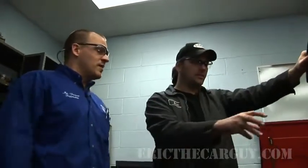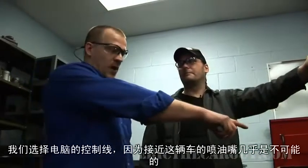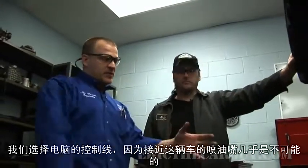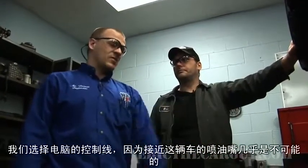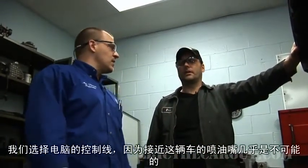We still might be able to zoom in on just the injector. Why would that be difficult? It's not difficult, but it might be muddy. I would agree. But we could go control wire at the computer, which is going to isolate the injector itself, and I would choose the computer because getting to the injector on this car is really not going to happen.